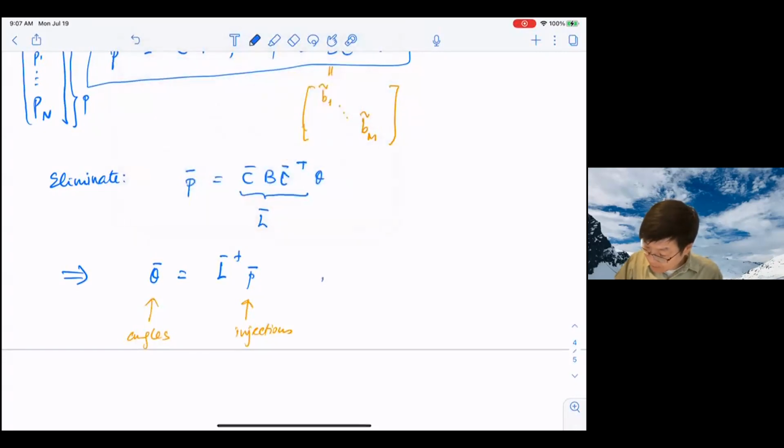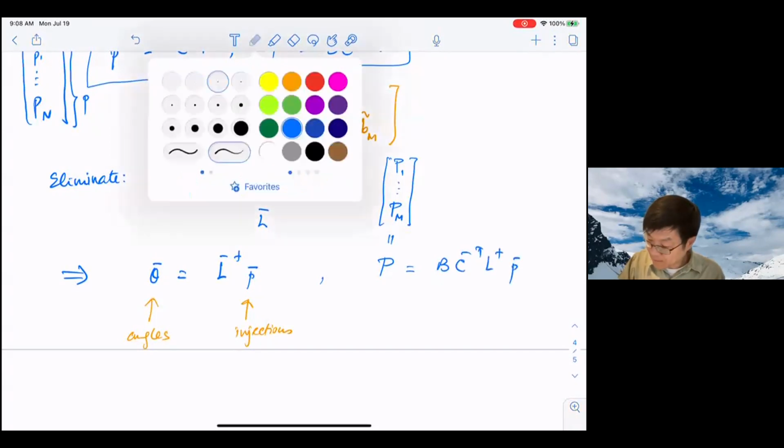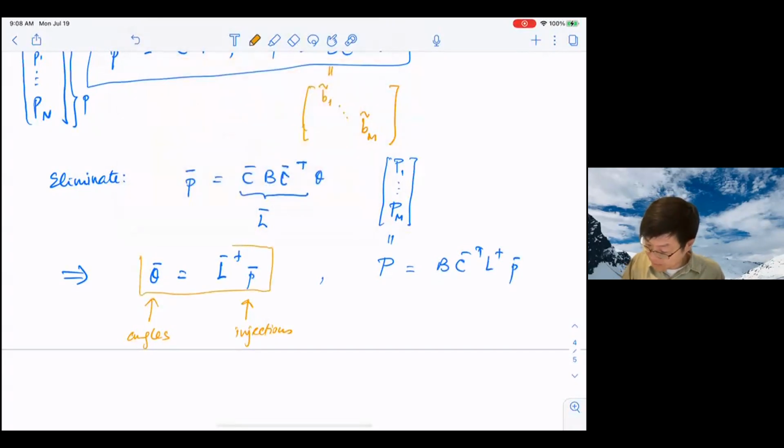And also the line flow. So this will be the vector of P1 to Pm. So the real power line flow vector can also be expressed in terms of the injection. And therefore, given power injections in DC model, we can explicitly write down the angles in the network and also the line flows on the network.